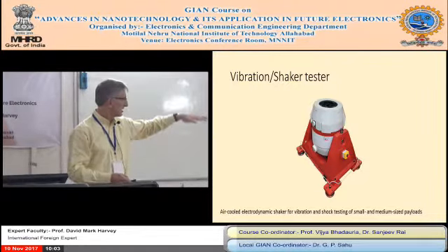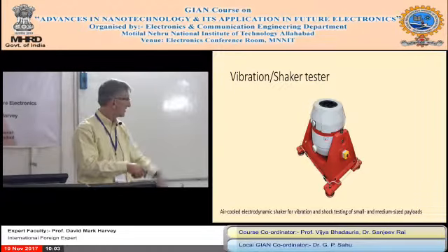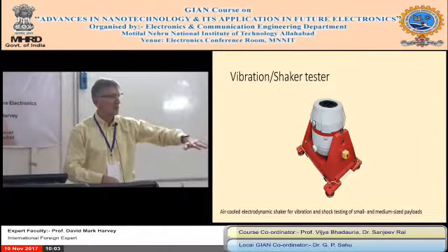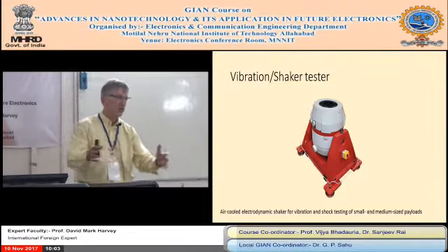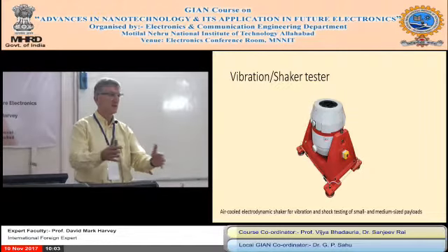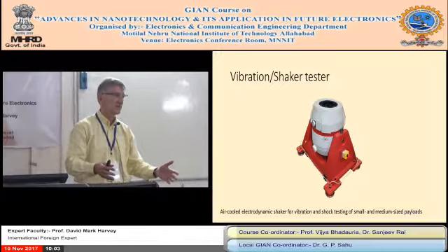So this is vibration in one plane. Most of these shakers, you can rotate 90 degrees. You have a big table, usually made of slate or some heavy stone, that goes in that direction, called a slip table. So you can vibrate up and down or both ways, because you have to consider all the different axes.